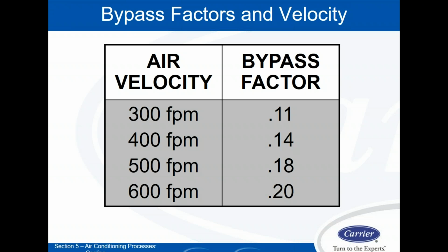In a lot of cases, when we are designing air handlers, the rule of thumb there, even though I said don't use rules of thumb, is that the maximum criteria for most air handlers is about 500 feet per minute. Otherwise, I start running a greater risk that the velocity pressure will blow the moisture that's on the coil off of the coil. I want the moisture to run down the coil and then drip into the condensate pan.